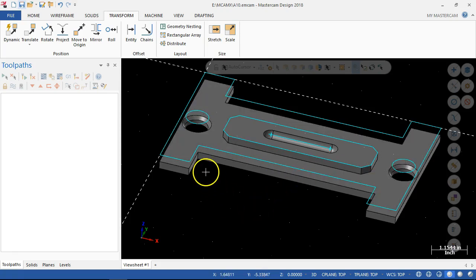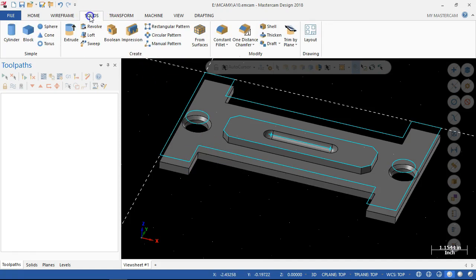But if I'm using a 3/8 inch tool and then a 3/8 inch ball end mill, I'm going to have some kind of corner geometry, or I'm going to be stuck with whatever the end mill will go into that corner, or I have to do additional operations. So that's usually the question: does that have to be a sharp corner? If I can put a radius in there, then that's going to be preference.